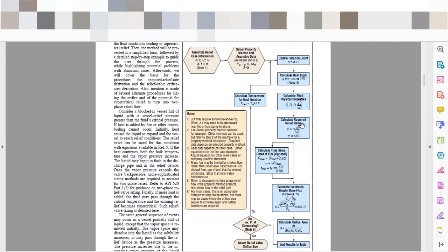With that, we will be able to calculate the volume flow and also the mass flow of the fluid. And considering that in the relief conditions we will have a shocked condition that leads to an isentropic release, we will be able to calculate the mass flux of the system based on isentropic conditions.